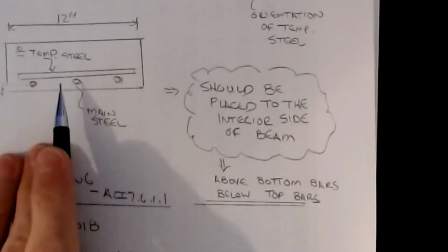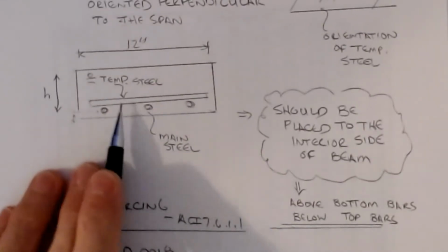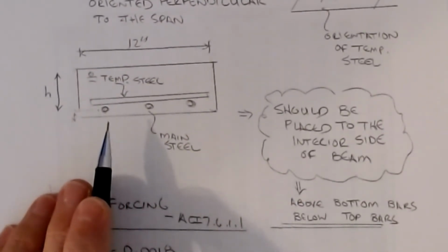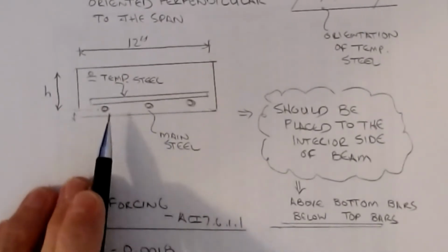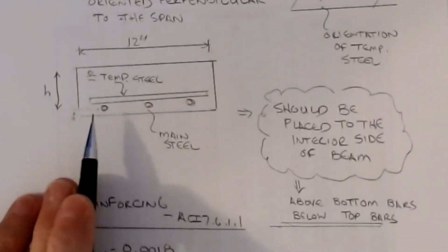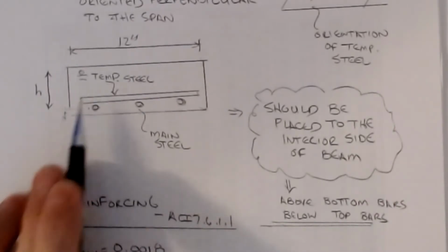This also illustrates that you've got to be really sure with your quality control program that the people that are installing these put the bars in the right direction and at the right location. So you've got to always keep your eye on that, because they can steal as much as, depending on the size of the bars, 7, 8, 9, 10% of your strength by putting these things in backwards.